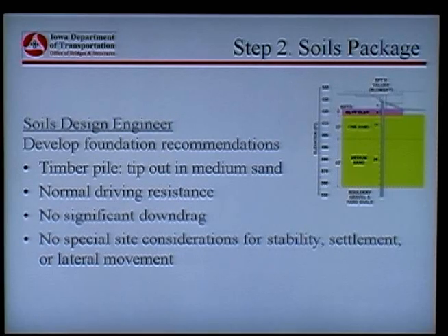The soils design engineer will develop the foundation recommendations. In this example it is a timber pile, tip in medium sand, normal driving resistance, no significant downdrag in non-cohesive materials, and no special site consideration for stability, settlement, or lateral movement.